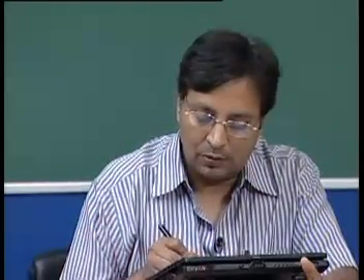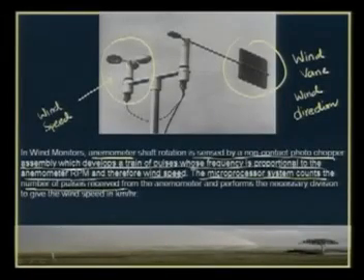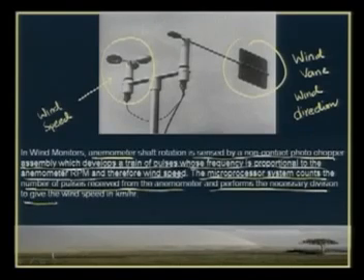The photochopper is placed inside; the shaft moves, and when it completes one round, the photochopper chops the light, and that pulse is taken up by the microprocessor and correlated with the wind speed. The microprocessor system counts the number of pulses received from the anemometer and performs the necessary division to give the wind speed in kilometers per hour.